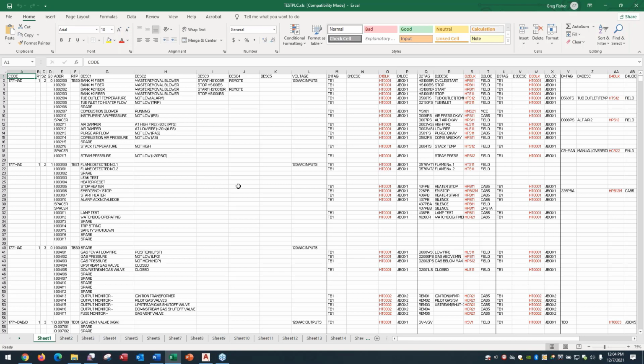The nice part is that out of the box, it comes with a couple sample ones. So at the very least, you're going to start with the correct format. You can make adjustments from there. So as an example, if I'm looking at this spreadsheet right now, column A, that represents the module that you're going to be using, the PLC module. That's the catalog number. The catalog number is tied to the symbol.